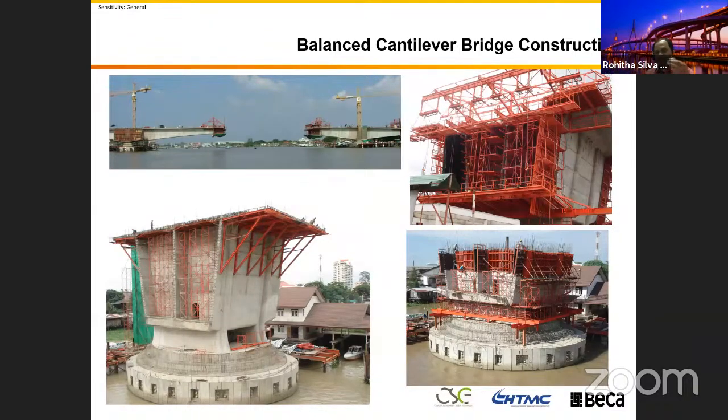What I am trying to explain up to now is, when you are designing a bridge, right? It's not that you are running a computer model and just calculating the bending, developing the bending moment diagram. If it is not steel, if it is reinforced concrete, we use pre-stress and post-tension; you design your reinforcement and leave it there.